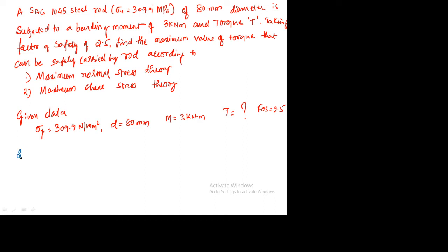So let us go for the solution. First we will calculate the allowable stress or working stress. This is sigma A or sigma E equal to sigma y divided by FOS.